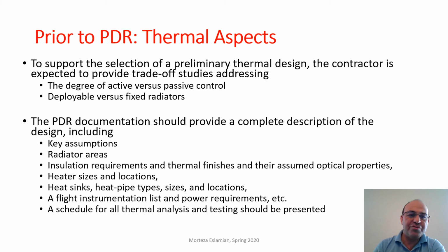Also, prior to PDR, to support the selection of a preliminary thermal design, the contractor is expected to provide trade-off studies addressing the degree of active versus passive control. As I mentioned before, it is important to actually use passive systems.